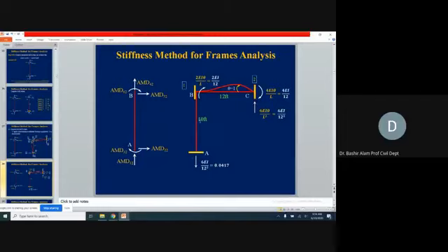Now again, this vertical member we are concerned with. So AMD 1,2, 2,2, again the reference for this labeling is again the AMs which we did. So AMD 1,2 is how much? It is minus 6EI over L squared. AMD 2,2, it is 0 here. AMD 3,2 again 0.